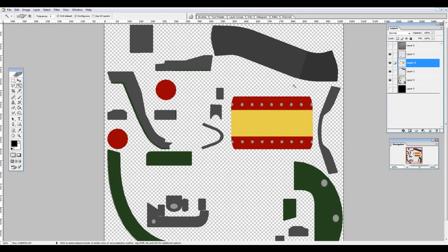So let's say I've got this part of the geometry, the texture which is red, yellow in the middle with gray. Let's say I want to select all of the screws, the nuts here in the middle. If I select them one by one, that will take a long time, especially if you've got dozens and hundreds of these things. So what we can do is go to the layer, press Control, and click on the layer thumbnail. This will select all the contents of this layer, including this and this. That's a quick way to quickly select whatever is on that layer.